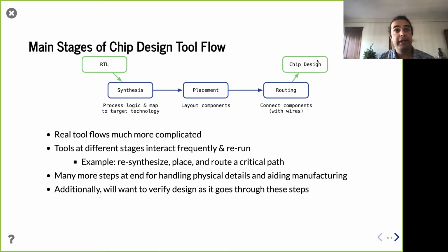And so there's an additional testing process there. And to aid that testing process, there's often hardware inside of the chip that is only used for that moment. So, this very expensive manufacturing machine is making chips and making an entire wafer. There's that moment when the tester, which is an actual hardware device, clamps on and talks to one of these chips or dies. And it's running diagnostics to see, was this chip properly manufactured, right?